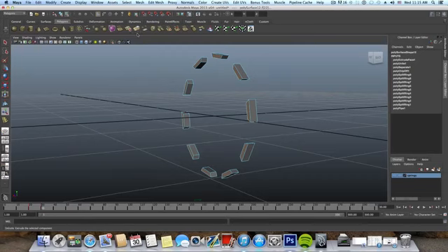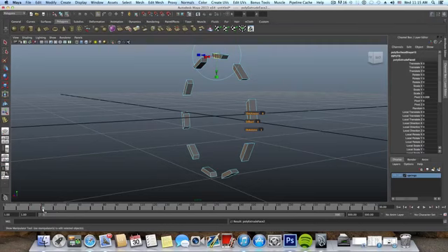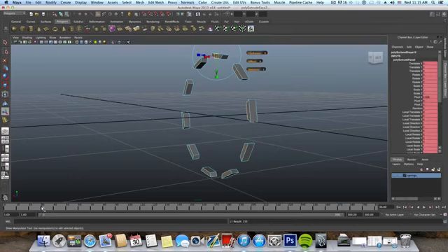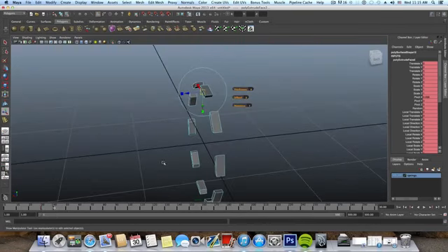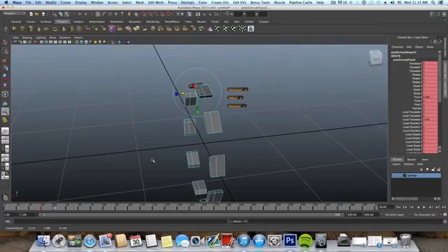So we will extrude this once, and then we will make sure that we first were in frame number 30, and we want to press the S key to record this, and we want this on 40 to extrude that way outside, and press S. Now we will rewind this manually and you will see what we get. Great. So now basically I've done this S key on frame number 39, but that's fine.